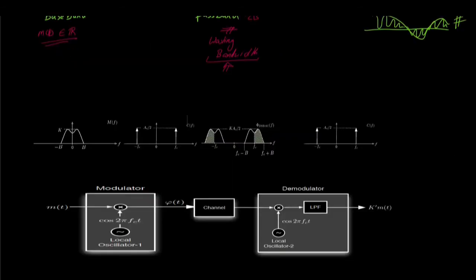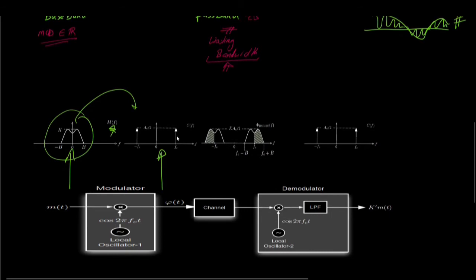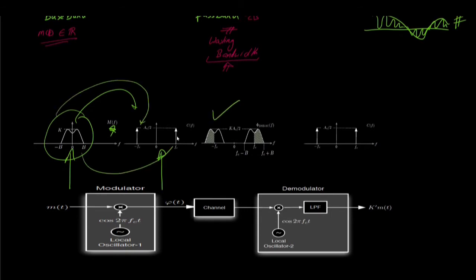Before moving to the simulation, let us again look into the frequency domain. So we have the low frequency, narrow band carrier. If we convolve this with this, it would appear twice at each end, and this is drawn over here, and then we again have this carrier represented over here. So over here the spectrum would be at 0, 2fc and minus 2fc.